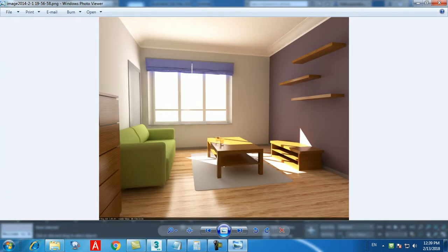Now, if I want to create this, I can create it in many ways. One, I can create a big box, apply shell, then create sweeps, top and bottom, then use ProBoolean to subtract the door and the window. Second way, I can create a rectangle, use outline for the wall thickness, and in the modifier list, extrude. Then boolean and all the things the same. Or I can go to AEC Extended and create walls. Again, boolean and sweep the same.